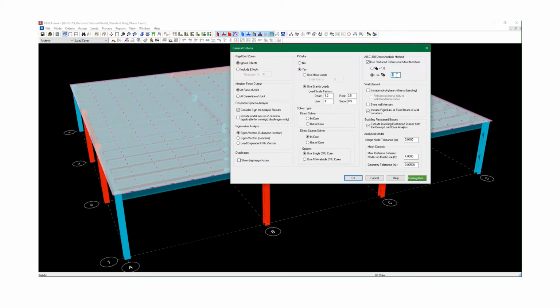And RAM may actually have a table, a report that provides you with the various values of tau sub b's that are found for each one of your compression members. And then you use the worst case scenario for the entire structure. Or if you design your structure to be relatively stiff enough or the load is not that high, tau sub b can be equal to 1.0.